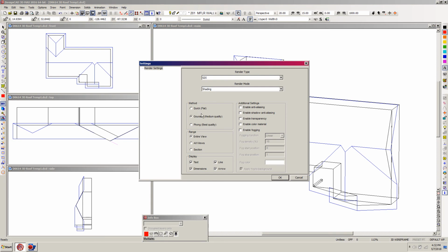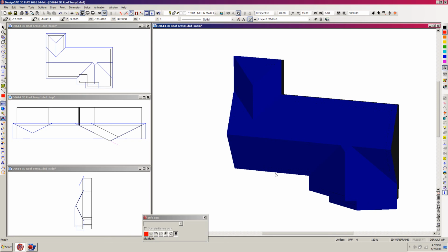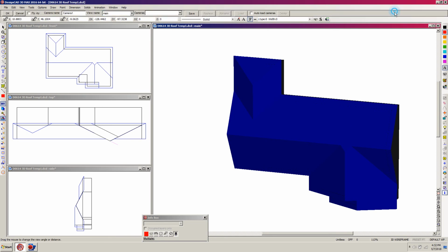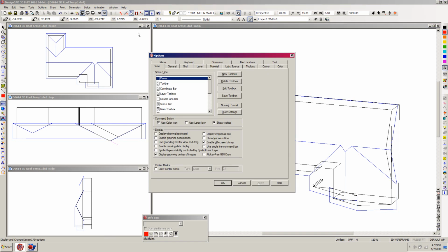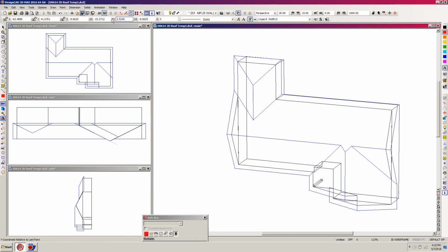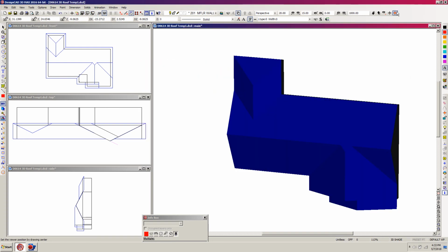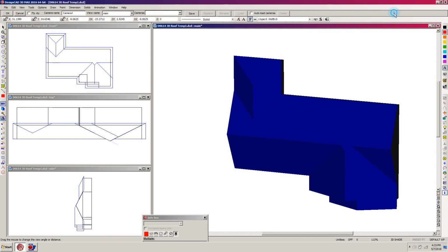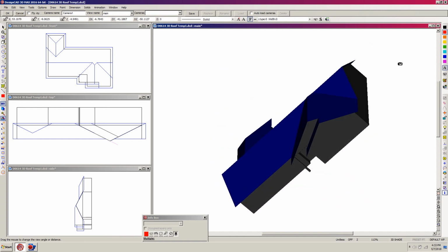We're not going to deal with it in this lesson, but let me go ahead and click on the shade, and okay, there's our shade. Oh, let me hit Q. And in view, we want enable graphic acceleration. Apply. OK. OK, so we'll hit shade again and click OK. And so now we use our set view by drawing center, and we can kind of scroll around here. And look, that's starting to look like a house.